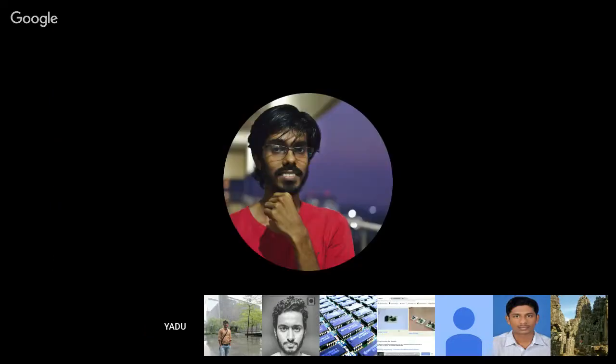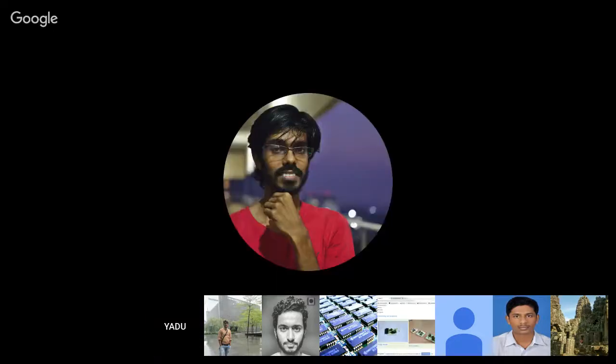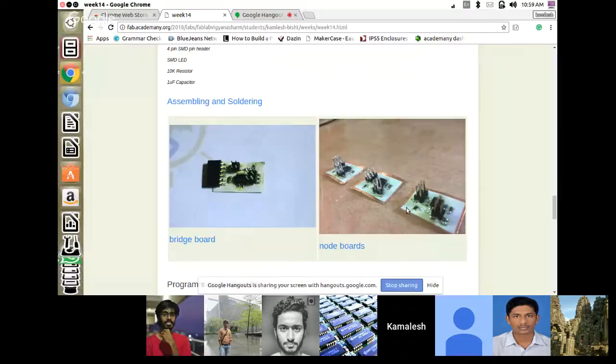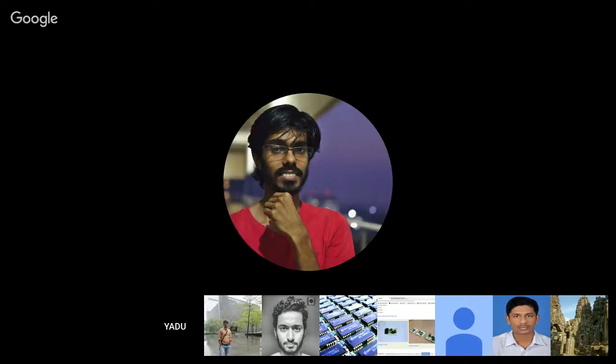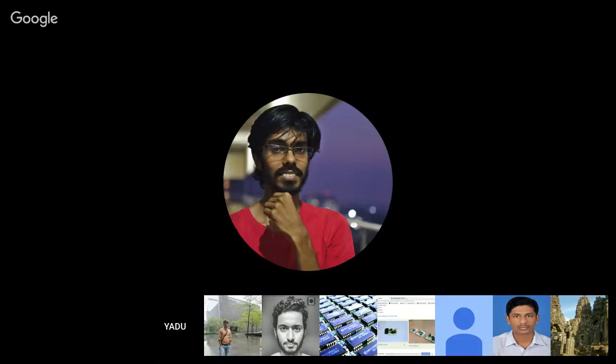If you have three boards, do any of them have a button or something? No, sir. Then you have to make at least one the master, and it should communicate with the two other boards. It should not be the PC. You should be able to run without the PC.